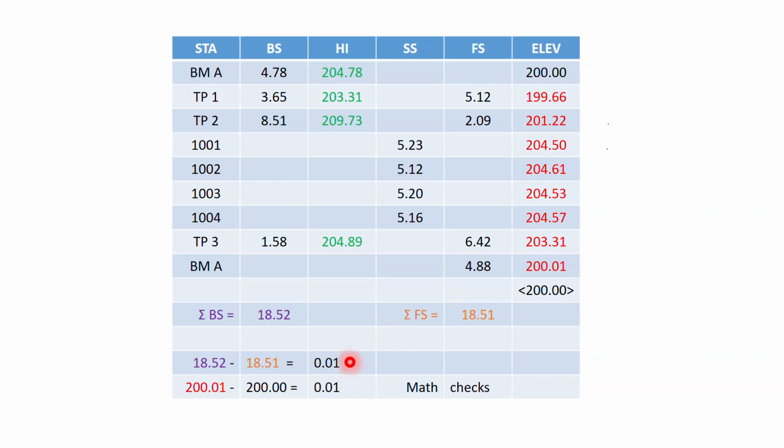If these numbers are outside the tolerance that you can live with, say you've eaten up all of that contractor's tolerance, they need you to be 5/100ths accurate, and you're already at 5/100ths in your confidence in your vertical elevations, you would want to redo that level loop. You would want to make sure you're more confident on your primary control points, if you had any that you were leveling through, before you went and accepted those elevations for future work.